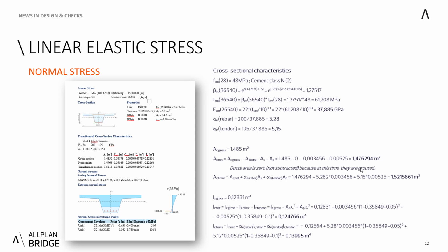And as I mentioned, we are performing the calculations at the end of the design working life, which means for the concrete bridge 100 years. Also, yeah, it can be 50, can be 70 if your projects allow it. But this beta factor that applies the extrapolation for 100 years multiplies this strength to be 61.2 megapascals.